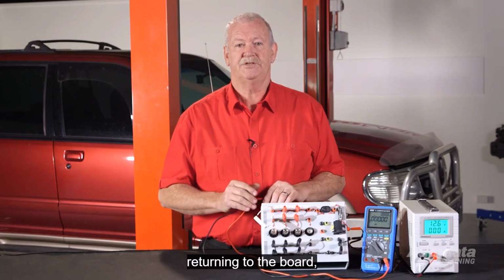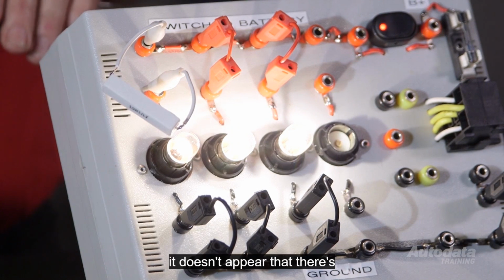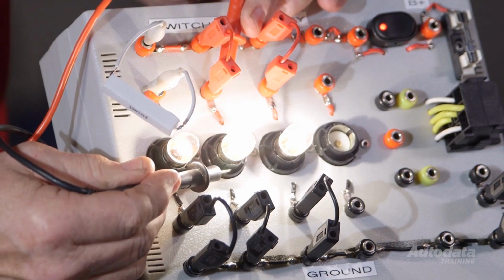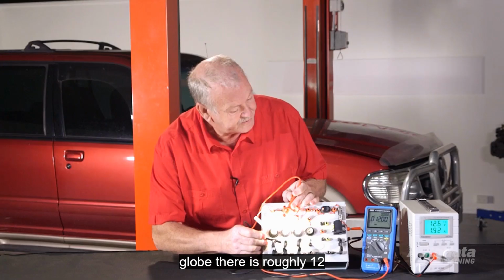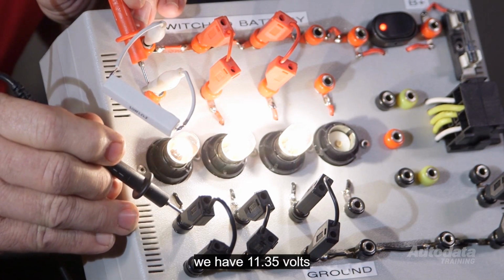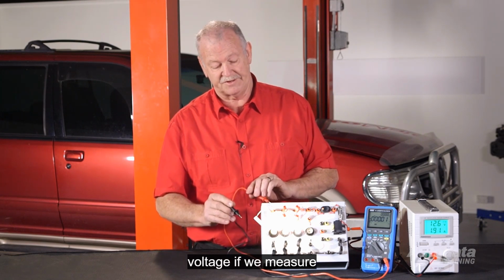Returning to the board, I have a resistor in series with one of the globes. Turning it on, it doesn't appear that there's much difference in the brightness of the globes. I'll measure the voltage drop. The voltage drop across that globe there is roughly 12 volts. And across this globe here, we have 11.35 volts. Even though it appears to be the same brightness, it doesn't receive the same voltage.